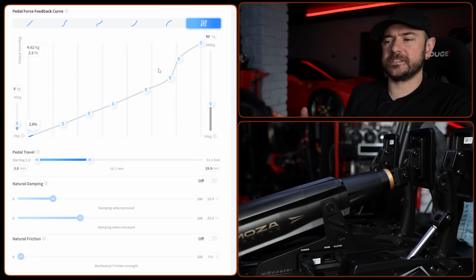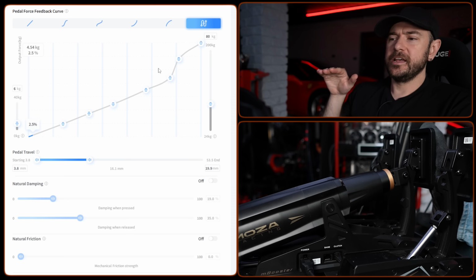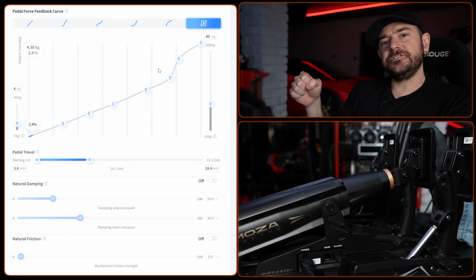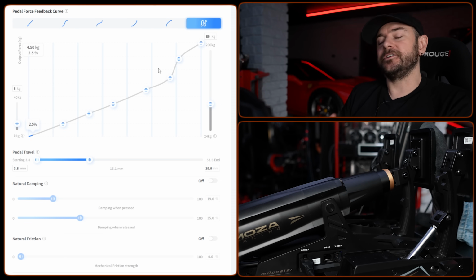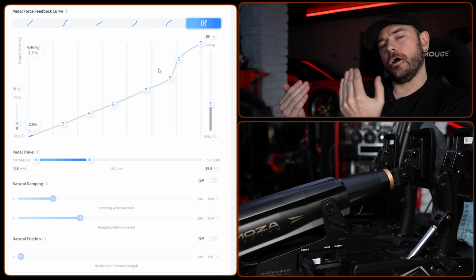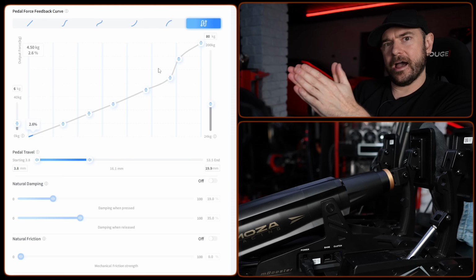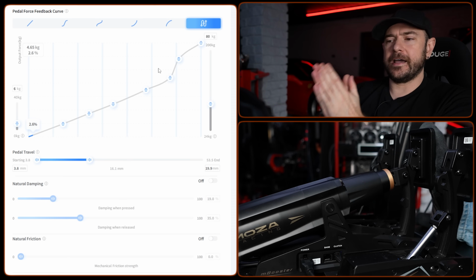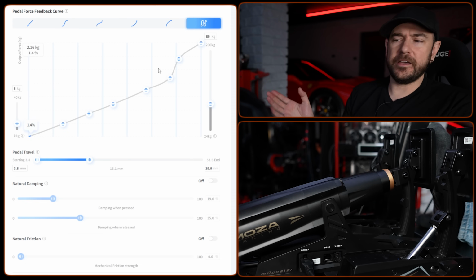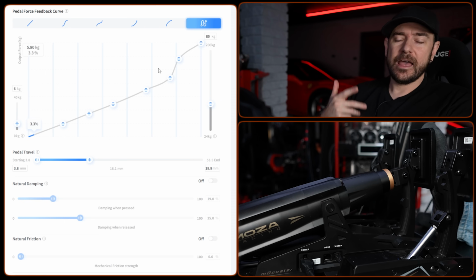So when you're braking or accelerating, obviously there's a certain amount of grip that the tire has available before it breaks traction and starts either sliding if you're braking or wheel spinning if you're accelerating. As you start to add steering angle on top of that as well, you're asking more of the tire. So what you need to do is start to trail off the brake input as you start to add steering angle so that you're maintaining that tire at the maximum level of grip available. And that's called the traction circle. There's a lot of information about traction circle available out there. You can do your own research on that, but that's a really important fundamental to sim racing and race driving.